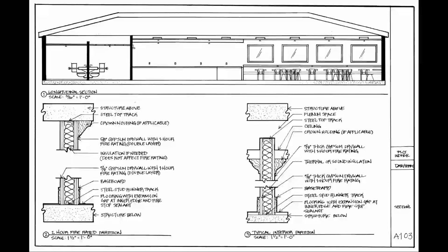And again, this is going to get much more detailed, but now at least you know how to show it on a floor plan with a section tag, and you know how to lay out a sheet to show an entire width of an interior space that shows how different rooms come together and the difference between typical interior partitions and fire rated partitions, and how those are used to compartmentalize space and smoke. Okay,